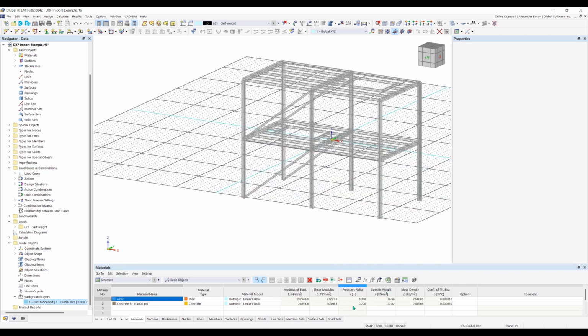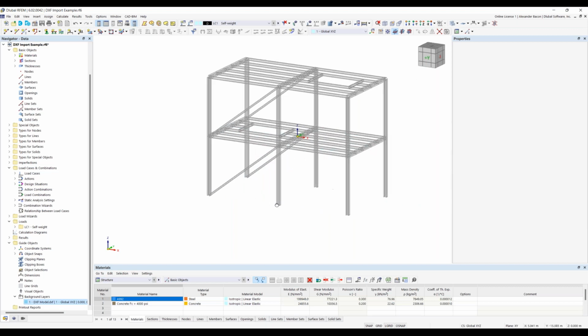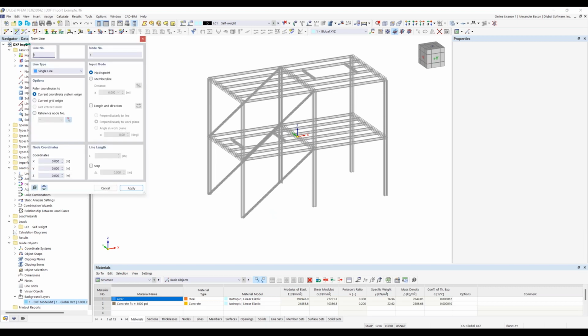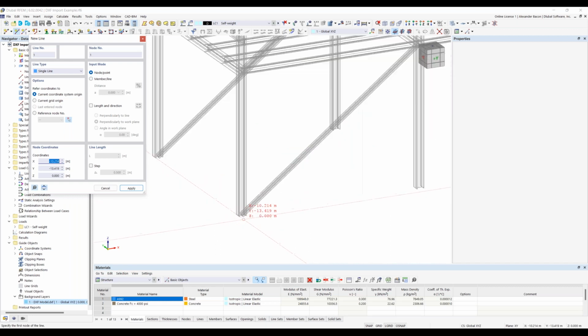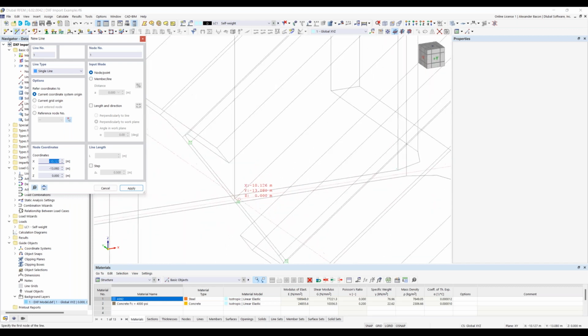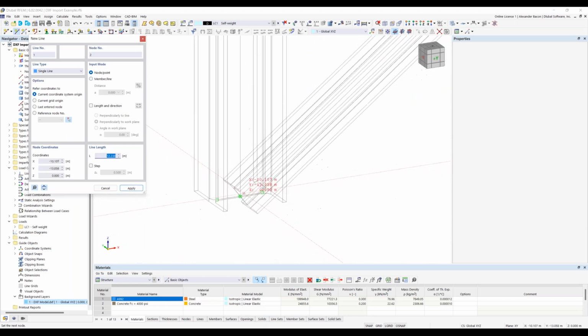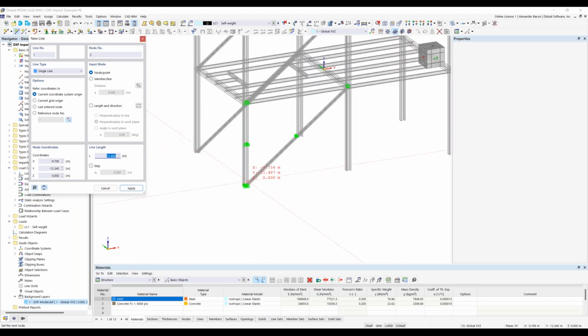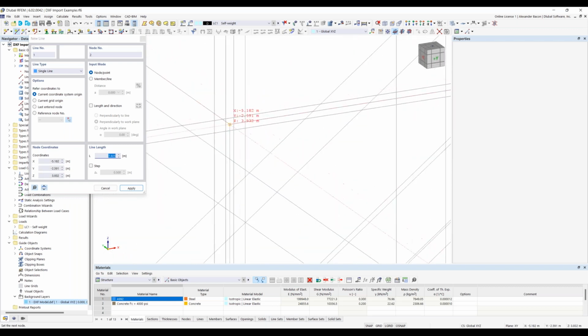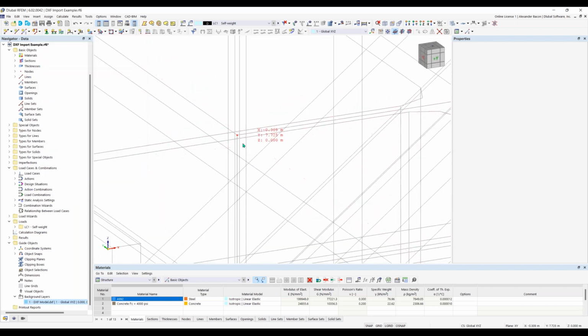So now we can use these background layers to model this. This is similar logic to the IFC file that I showed. And I'll just do an example real quick. So we can draw a line, a center line again. I'm going to use this column again as an example, so I can zoom in here and snap to this point if you have your object snap settings turned on. And then I'm going to go to the top here, and I can snap to this point,